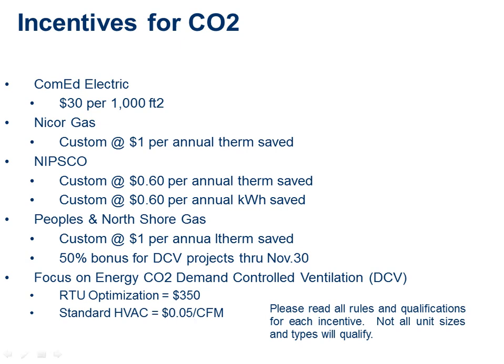All right, let's look real quick and see if any other questions pop up. Nathan says, it has been our experience that CO2 sensors have difficulty with accuracy, calibration, and maintenance. Because of this, sensors are often disabled by building engineers. Have you had similar experience? It seems there must be better options for DCV. All right, a couple different things there. CO2 sensors have had an accuracy issue over the years. I'm going to talk to you about some sensors that came out 6 or 7 years ago that have avoided that accuracy issue. Accuracy on some of those is a calibration guarantee.